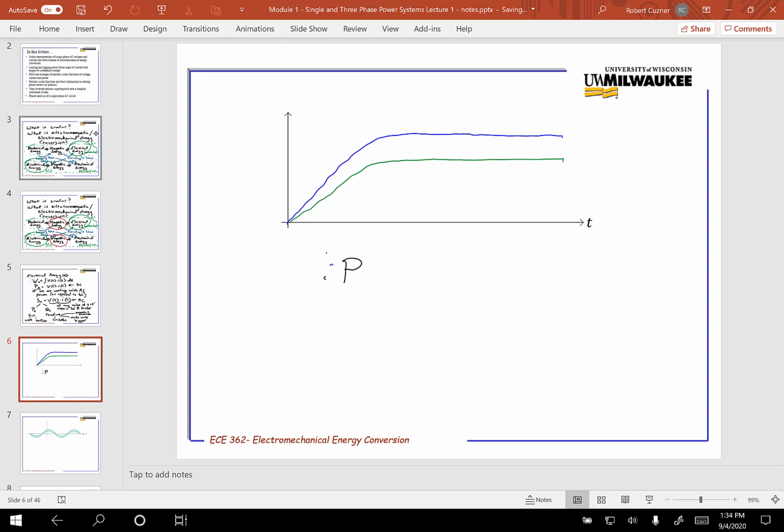One is in units of volts and one is in units of amps, and eventually we want to look at power, and I want to look at all of them on the same axis. So what we do in per unitization is we establish a base voltage. So there's a V base, and we would also establish a base current, I base.